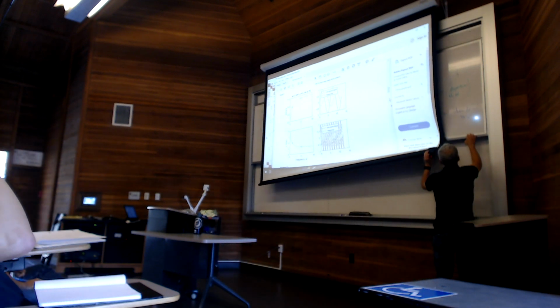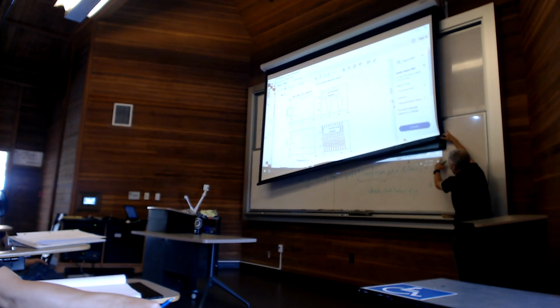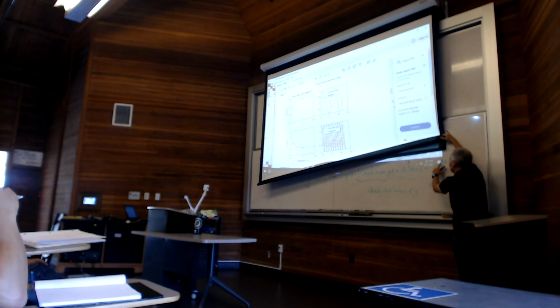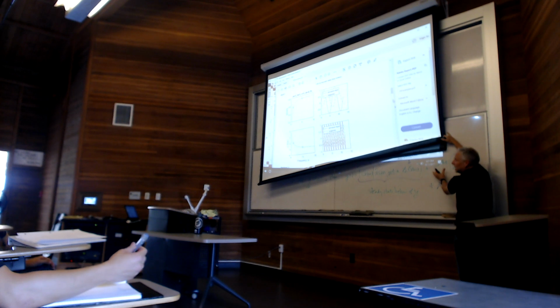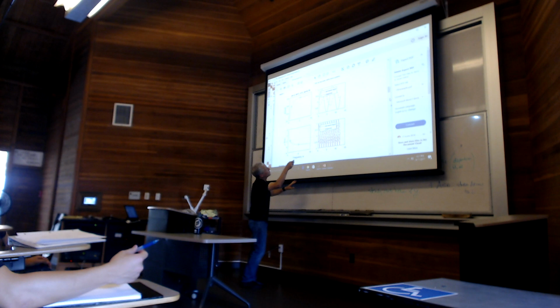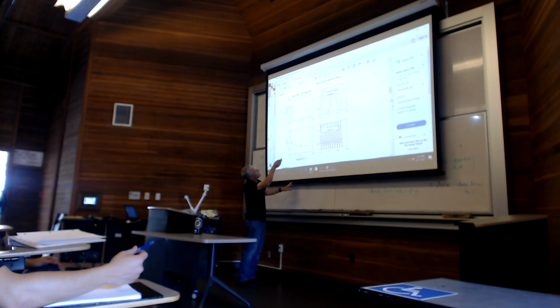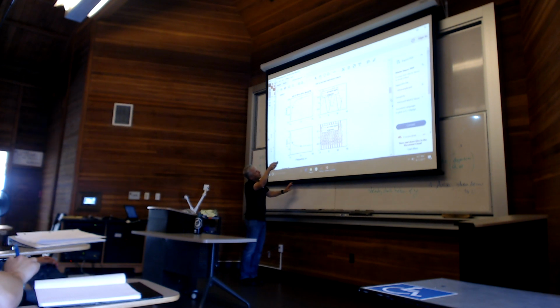How quickly should it take to get there? Well, remember this term that's here, it's decaying with the time constant. In this case, A was -1, so the time constant is 1 unit. So this term, however big it is, after 3 time constants, we know it's only about 1/20th of what it was. Sure enough, after certainly 4 time constants, this is starting to look like the sine, whereas initially it was completely not right. In the first couple of time units it's not right, but then it's settled down to this sine wave.